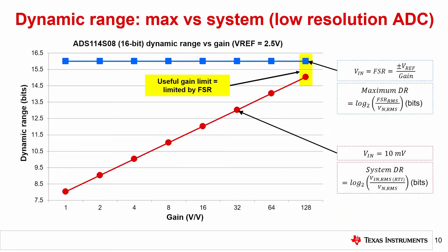It is important to remember that datasheet dynamic range values tend to demonstrate the best possible ADC performance at the given conditions using the maximum input signal. If you applied a signal smaller than the maximum, for example 0 to 10 millivolts, applying gain is essential to get the best noise performance and improve your dynamic range.